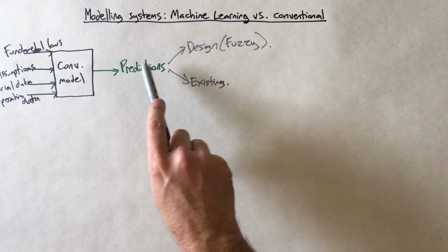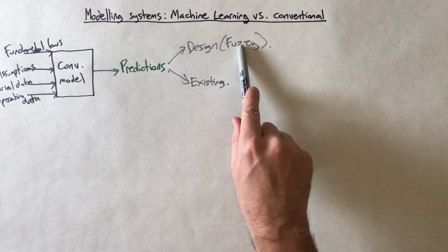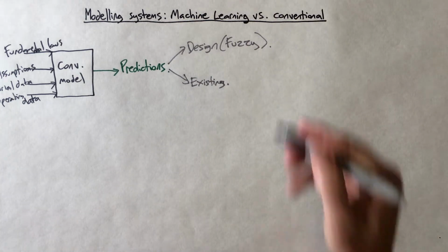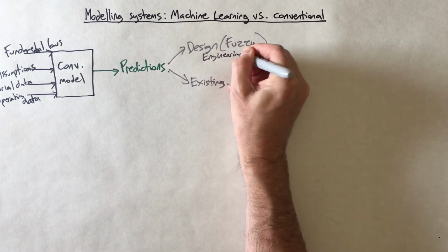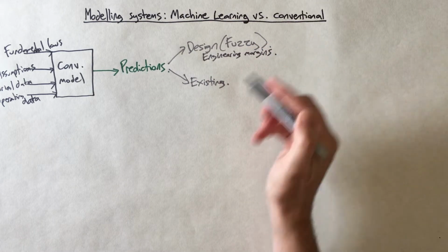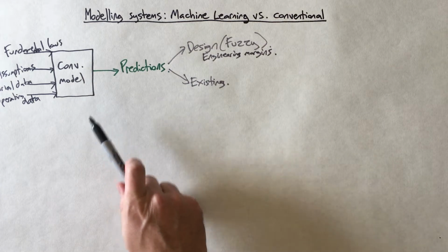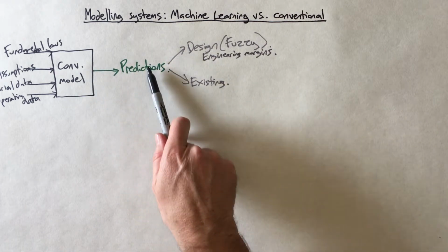Now, we start to run into a bit of an issue here. I mentioned before that when you come up with these predictions, they're often a little bit fuzzy. For design, we cope with that by implementing engineering margins, or safety margins, you might call them. So let's say in my example before, we come up with a design, we decide that a chemical reactor has to be 3.5 cubic meters is our prediction.